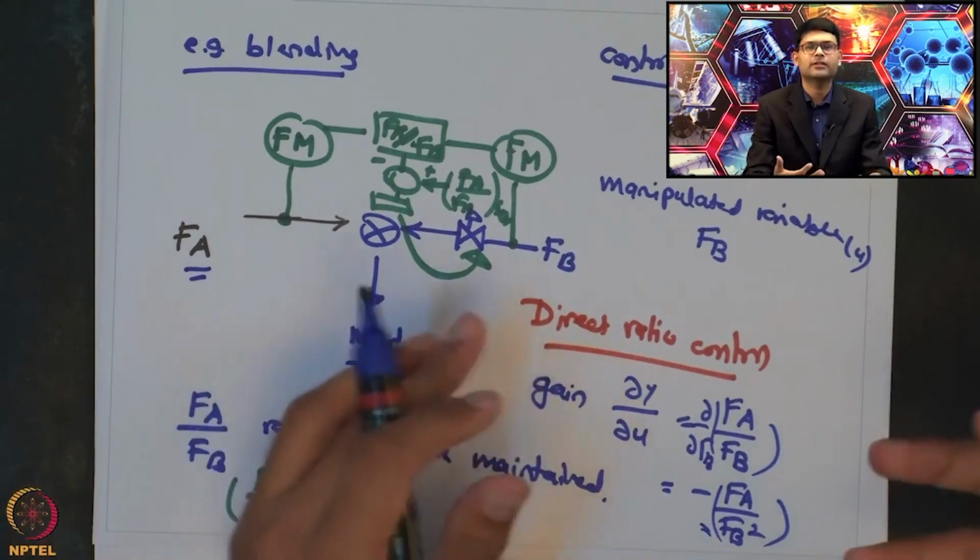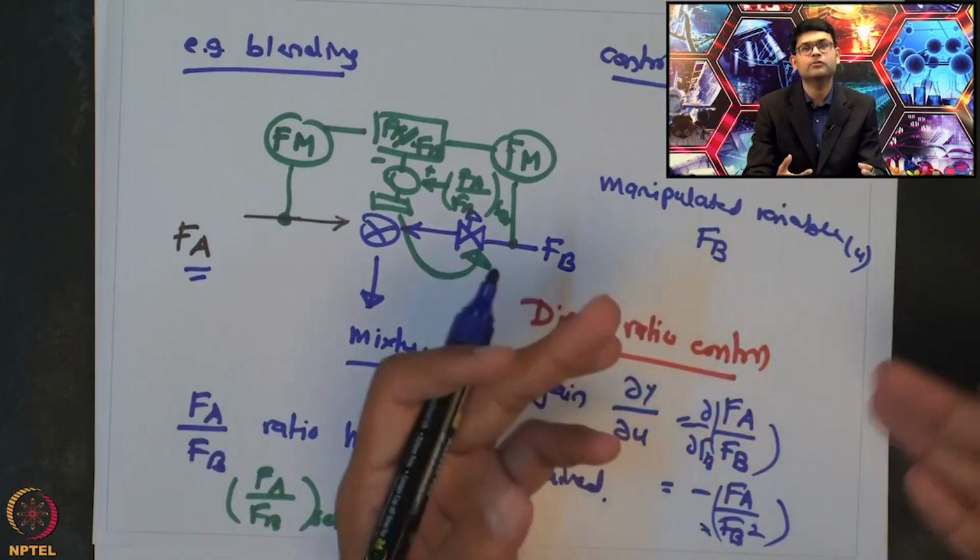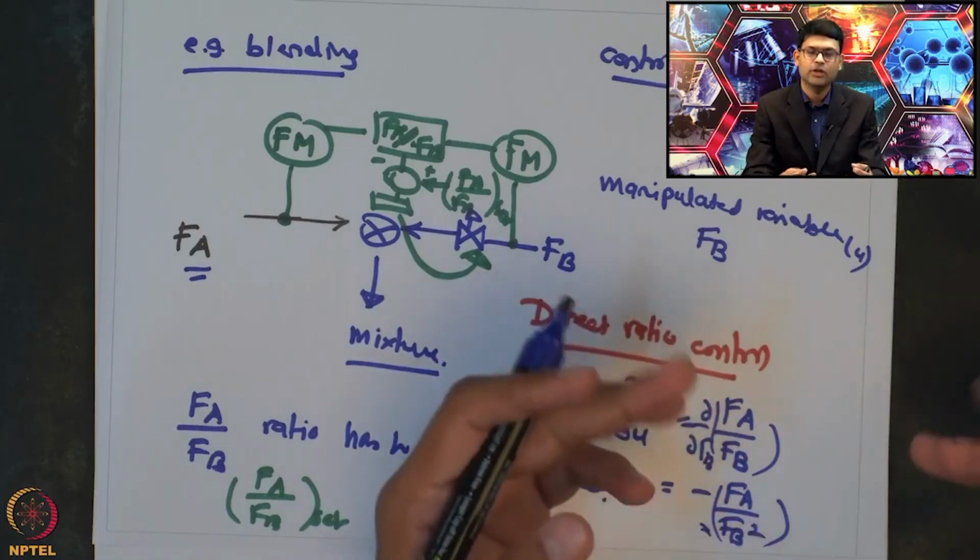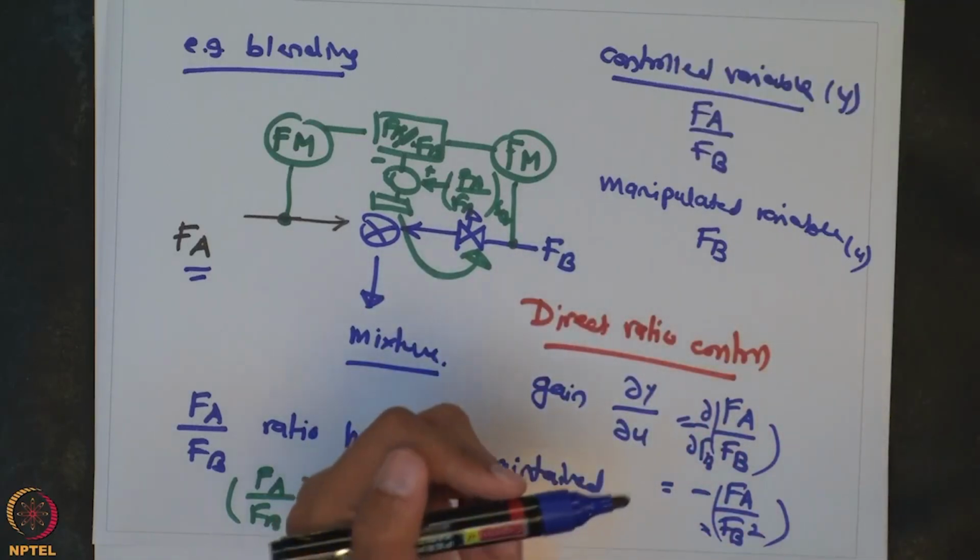And we have seen that the controllers which we have seen so far in terms of PID control are all linear controllers. So as the process gain changes, the optimum controller settings are also going to change depending on the value of the disturbance, and this control strategy may not give you best performance throughout the disturbance window in terms of how much disturbance it can tolerate.